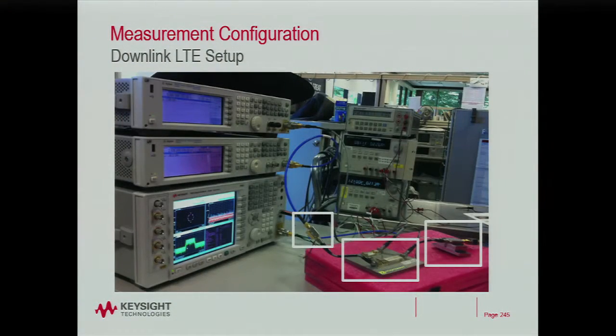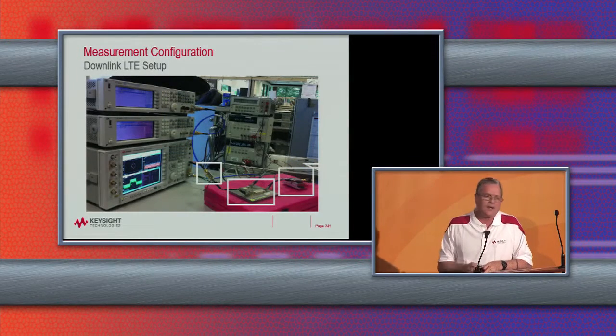First, I want to go right to an experiment that we did. We built a little 5G transmitter, and this is the test setup here. And here are some off-the-shelf components, and you see those in the white boxes there. On the very left is a Mini-Circuits IF amplifier, and then there's an X Microwave block in the middle that does an up conversion to 18 gigahertz. And then at the end we have an API Technologies amplifier. So this was our test setup.